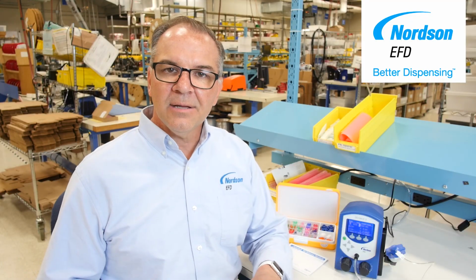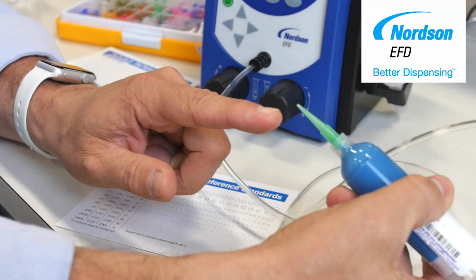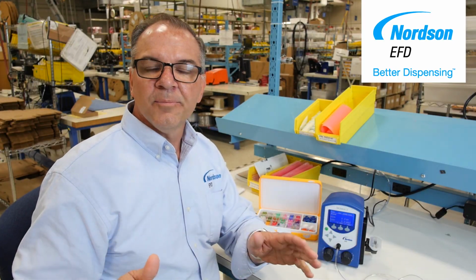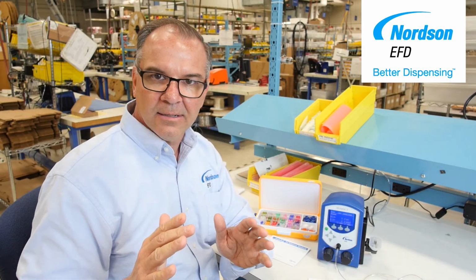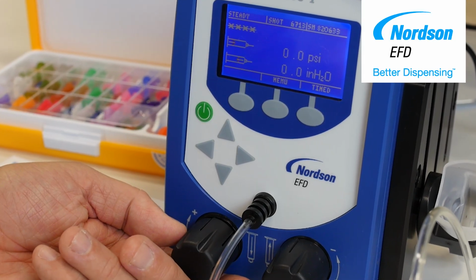Once we've selected the tip, now it's time to set the air pressure. Here's what I like to do. Put a new dispensing tip on the syringe. Now you would have selected this tip from the diameter of the dot that you're going to make. On your dispenser, start at 0 air pressure and slowly work your way up.